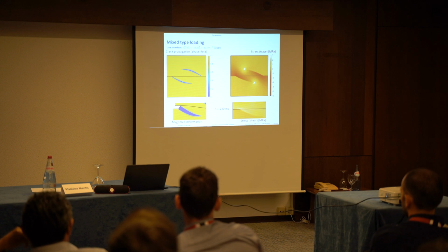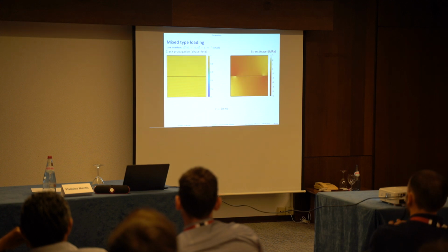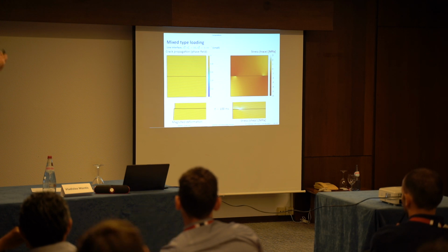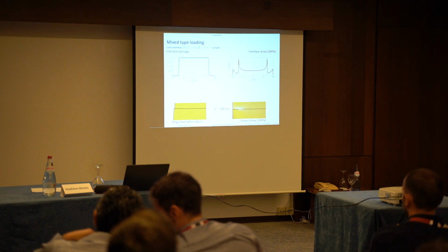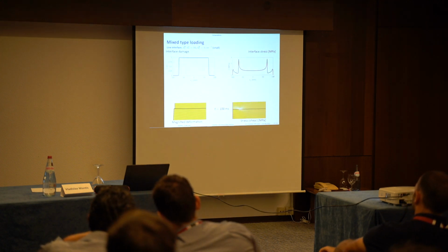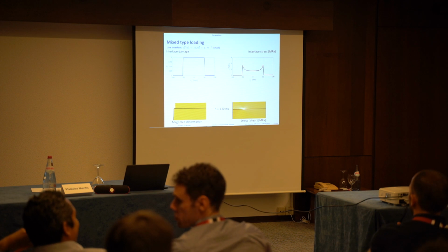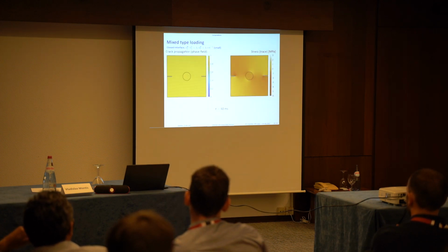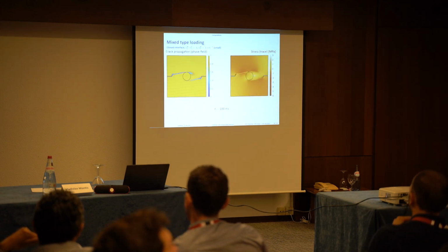We see that the picture is principally the same as before. And finally, we see that when we have small GC at the interface, the crack may appear actually on the interface due to loss of passiveness in the interface. So we can check it directly on the interface because we have the interface variable there. So I skip this and go to this.